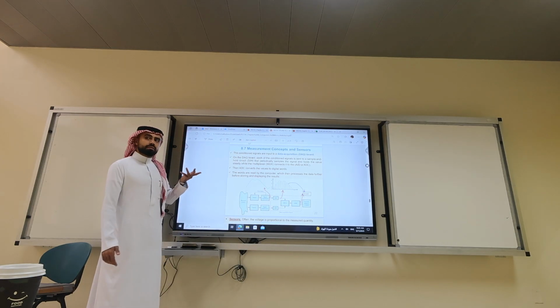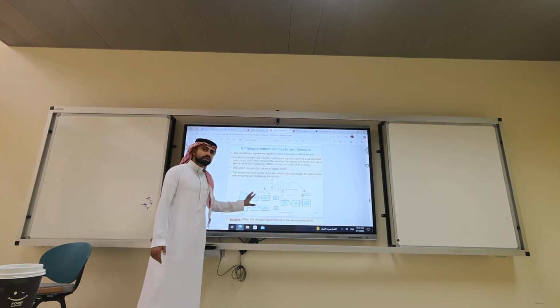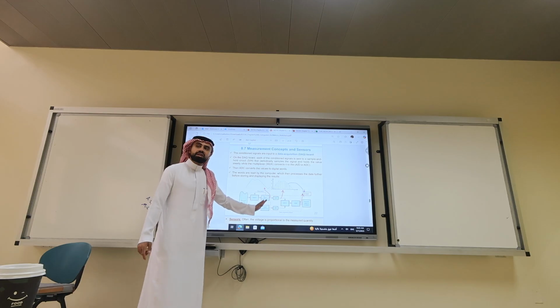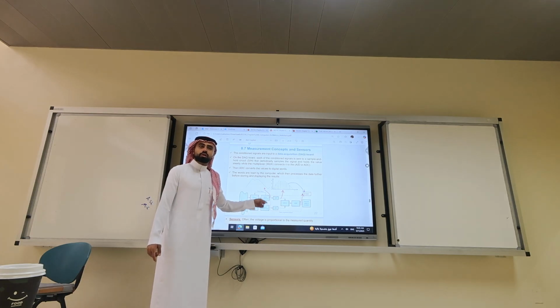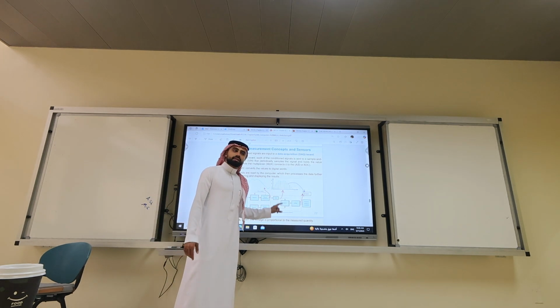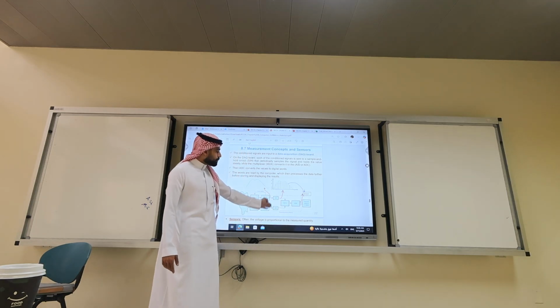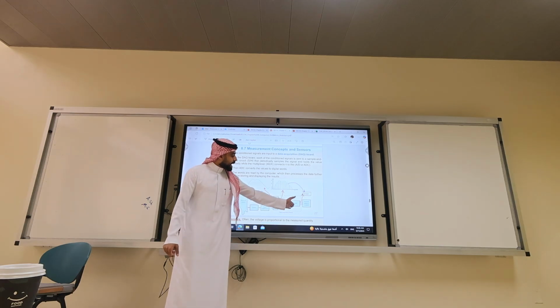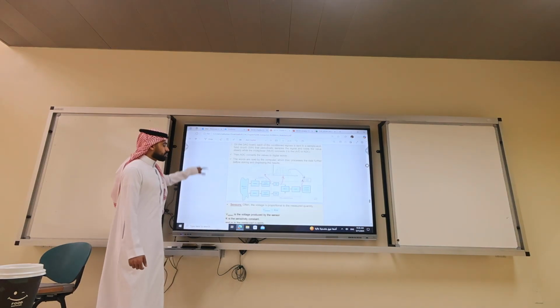So what did we learn today in this chapter? We learned that sensors are just the beginning of the story. The problem with sensors is they give you current, they don't give you voltage, they give you a noisy signal. We go to the signal conditioner. This is very important, ya shabab, if you work with SABIC or Aramco. So what is a signal conditioner? It is a device that removes the noise and gives you proper voltage. Then it goes to the DAQ. What is DAQ? Data acquisition board. What does it do? Sample and hold. Take a sample and hold it. Mux is multiplexer, meaning to choose the signal. The last component is the analog to digital converter.